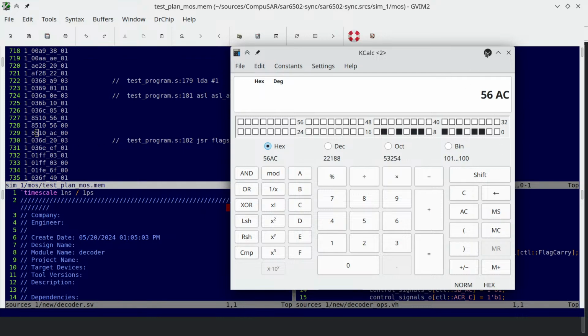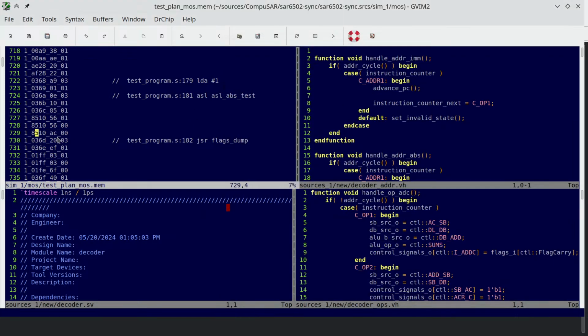And the point here to look out for is the fact that we read it from memory and write it back into memory. This style of commands are called read, modify, write. And that's what will be implemented now. So far, everything we've done, the difference between the opcodes was mostly about the addressing mode.